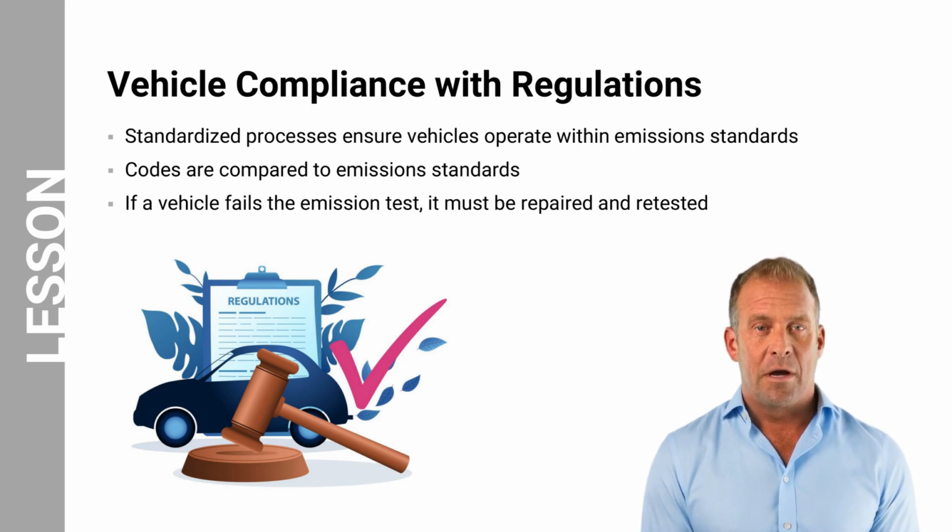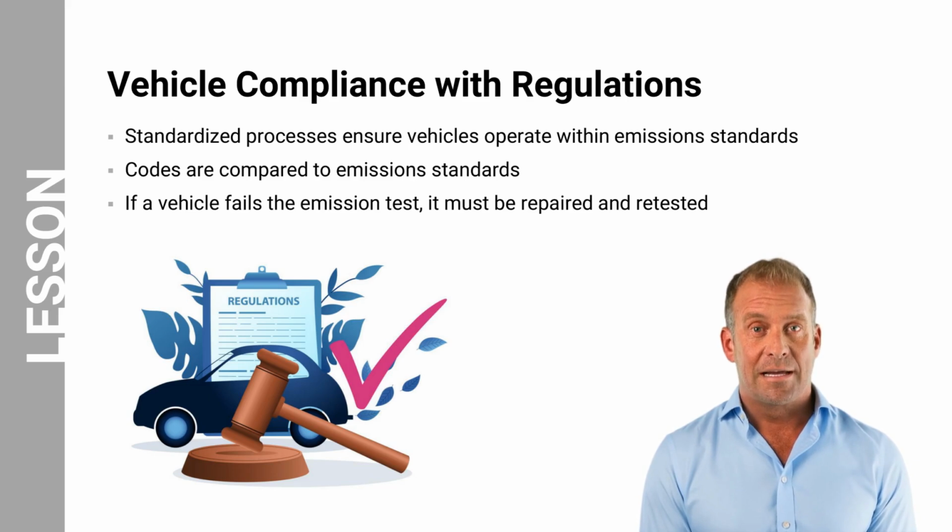This helps reduce the number of harmful pollutants released into the air, which can contribute to respiratory problems and other health issues. Second, OBD2 provides a way for regulatory agencies to enforce emission standards by requiring vehicles to pass emissions tests. Depending on the states within the U.S. or internationally, an emission test might be required. During an emissions test, an OBD2 scanner is used to read the error code stored in the vehicle's OBD2 system. The information is compared to the emission standards set by regulatory agencies.